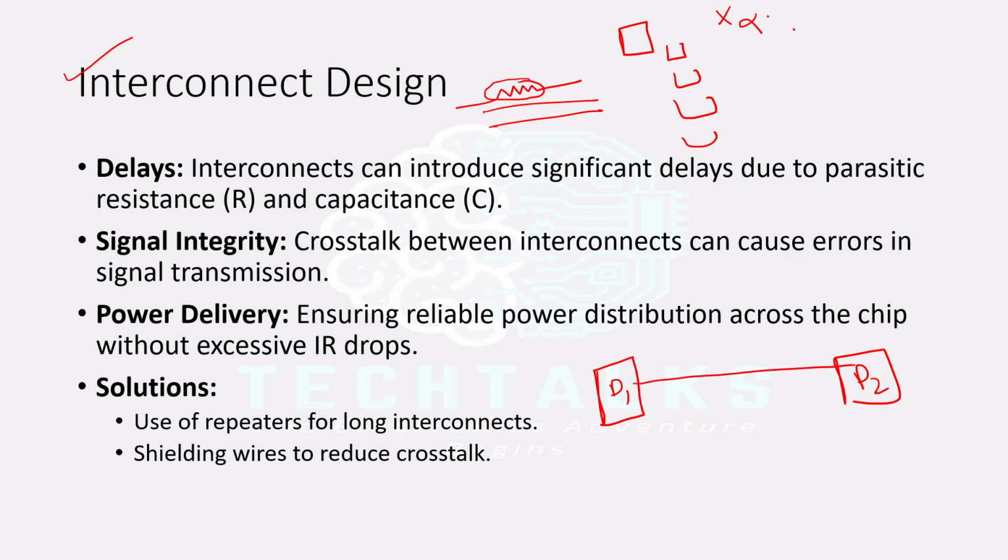When you connect both with a simple wire, we assume that it has no resistance, so the effective voltage drop across it is I times R, which is 0. But in the real world it has some resistance, so I times R is not equal to 0. So if here we have V, here we will have V minus delta V.